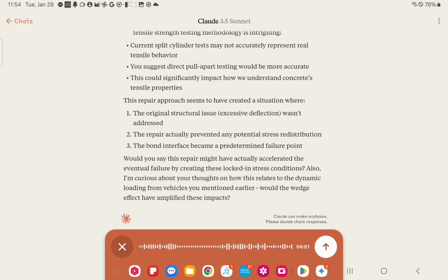Let's say that. Then they strip the forms off. They look at it. This is just theory now. I don't know what it looks like when they strip the forms off. But I do know that after the building was open, they immediately had to do this repair right down this mid-span. Are there other repairs that had to be done with those amount of spans? Not that I could find. This was the only one that had a 20-foot, 1-foot span. The others had different span and skewed column issues. But this was the only one that presented in photographs after the fact that showed that the epoxy injection, foam injection, was done down the mid-span there, literally in photographs.